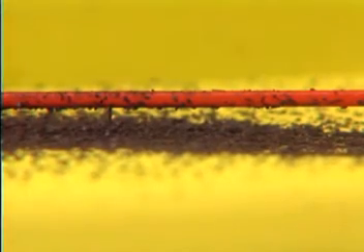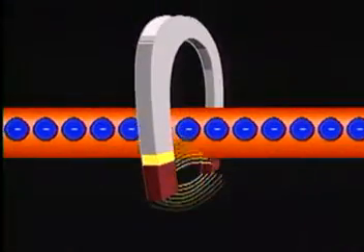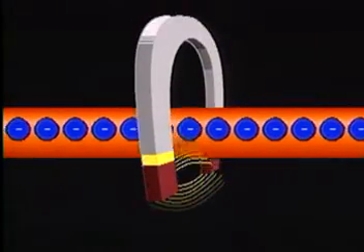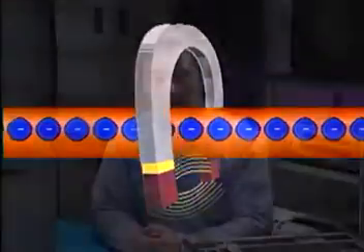This is electromagnetism. But the reverse is also true. Magnetism can induce a current flow. But before doing a demonstration, let's consider some important safety requirements. Since the human body is able to conduct electric current, you must make sure you are properly insulated from any conductive paths. Here are some personal precautions.